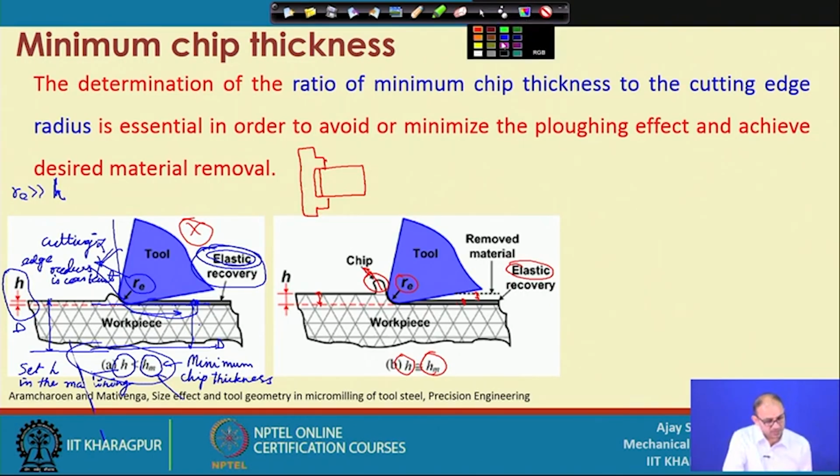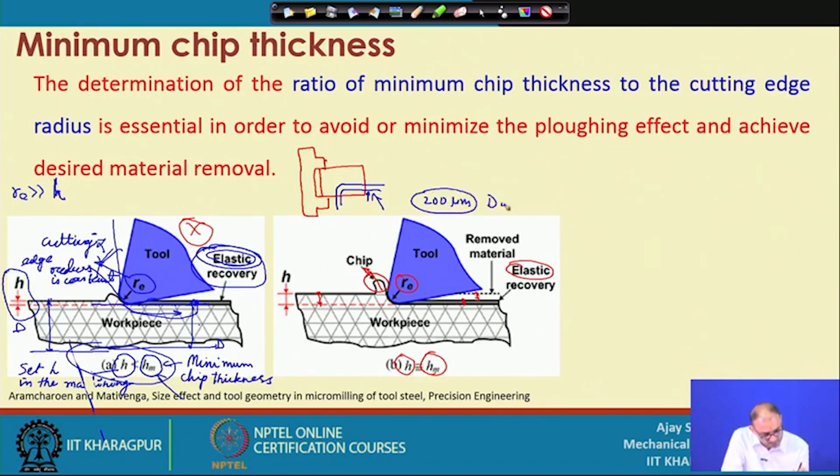Now, you are removing the material, considering that you needed 2 passes to reduce this particular diameter, and this is the 2 pass, this is the first pass. Now, considering the first pass you have removed this material, right. So, whatever depth of cut you are giving here, suppose depth of cut we have given is 200 micron, 200 micron depth of cut.